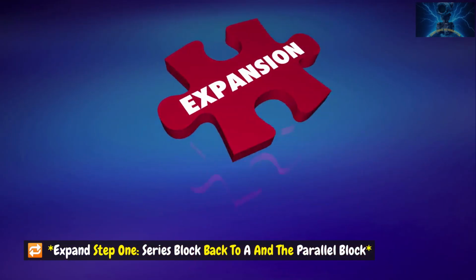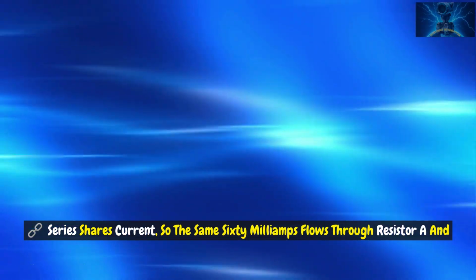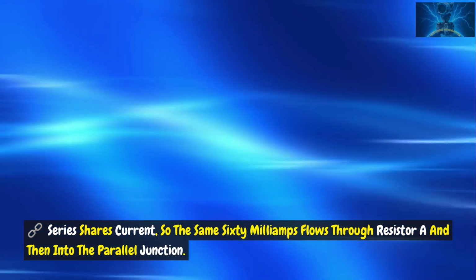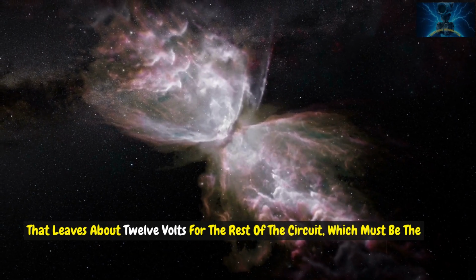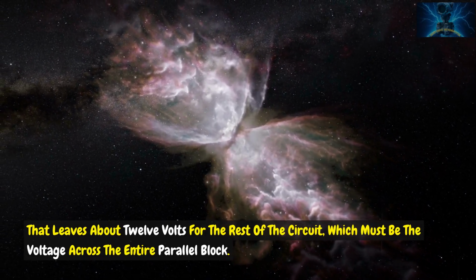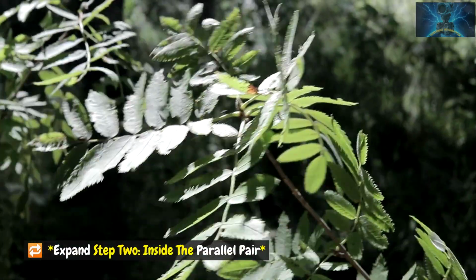Expand step 1. Series block back to A and the parallel block. Series shares current, so the same 60 milliamps flows through resistor A and then into the parallel junction. The voltage drop across A is current times resistance. 60 milliamps times 200 ohms gives about 12 volts. That leaves about 12 volts for the rest of the circuit, which must be the voltage across the entire parallel block.